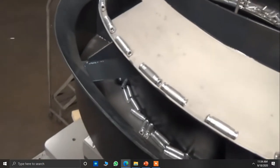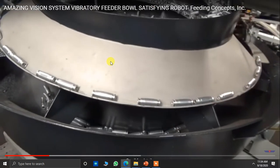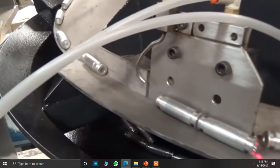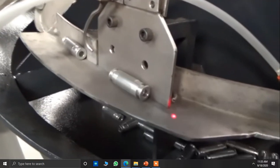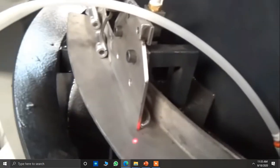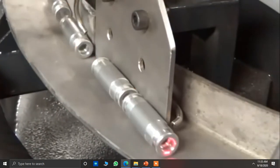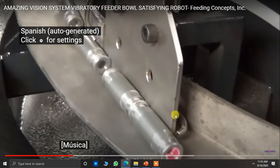So here the first orientation is happening. That means each component will move in a particular sequence. Here there is a laser which will check whether the object is placed in a proper position or not. Whenever there is a component which is rejected or not properly oriented, it is rejected by an air gun. You can visualize a small air gun here.